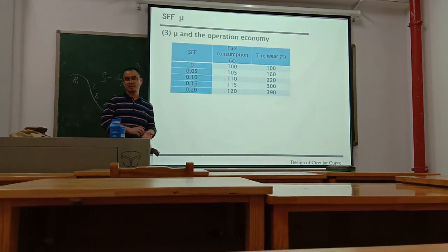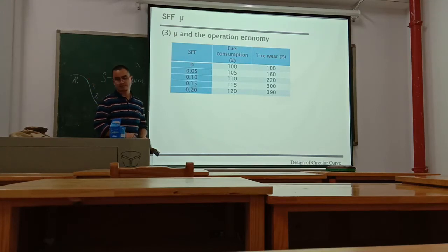The relationship between mu and operation economy: if mu, the side force factor, is very large, the fuel consumption will increase, and the tire wear will increase.